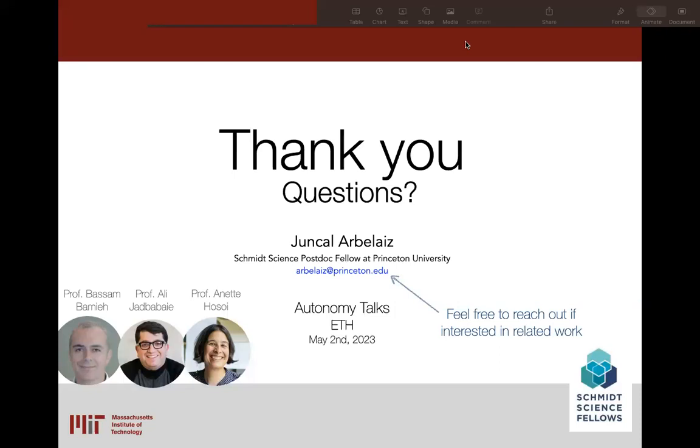My feeling is that in that context you will have an additional dimensionless group, which will be the ratio between your spatial extent, your domain, and the decay rate of these kernels in the spatial invariant setting. This ratio will tell you how much your boundary conditions affect the controller. So what you could do is design the controller or the estimator as if it was spatially invariant, and then add some correction terms towards the boundaries that will account for that lack of spatial invariance. I think this is how you could go about it.